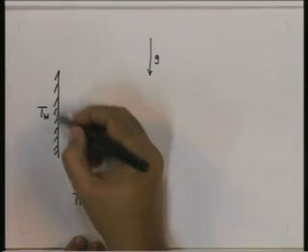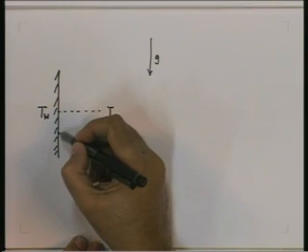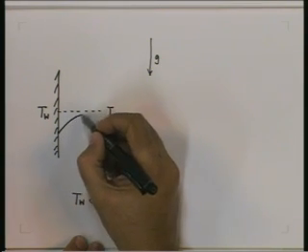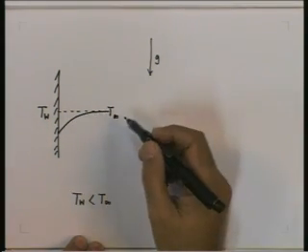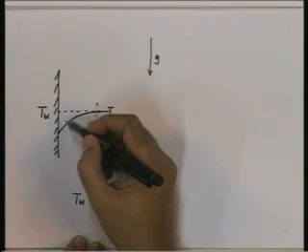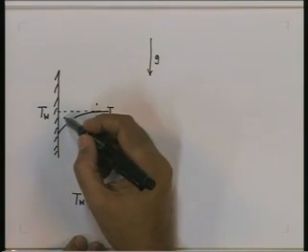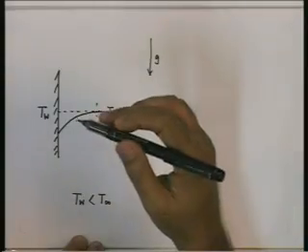Now what happens? The wall temperature is lower, some layers near the wall cool down, there will be a thermal boundary layer, and because of this lower temperature the density here will be higher, the fluid will tend to sink because of higher density. The net effect of buoyancy would be to move denser fluid layers downwards.